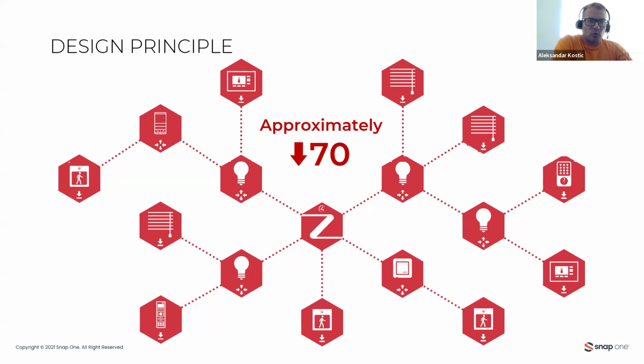That means you should avoid two Control4 controllers acting as Zigbee access points too close to each other, or having devices in between, so a device is not sure should it connect to the first or the second Zigbee mesh. So each Control4 controller is a mesh for itself now.